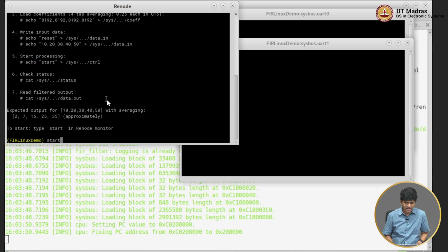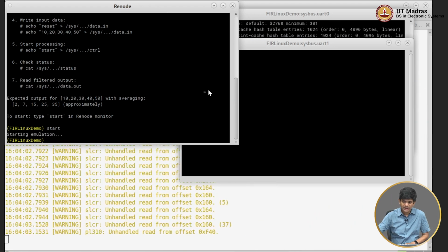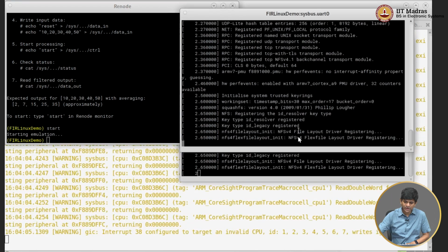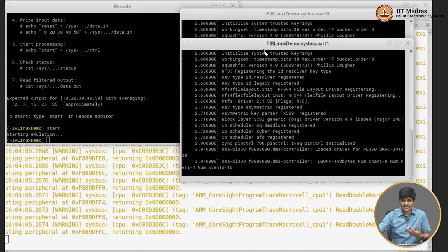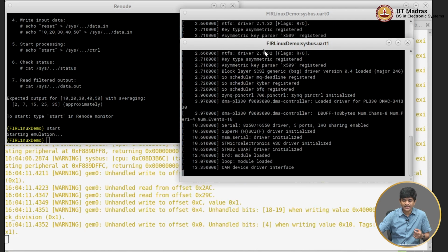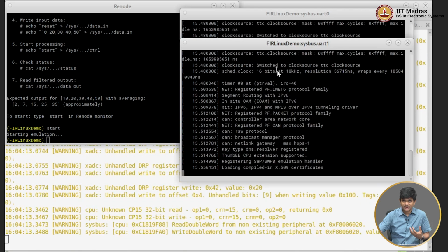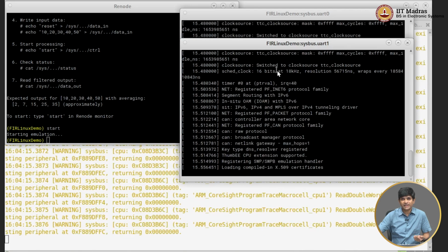So I'm just going to go ahead and start booting into Linux, and this behaves exactly the same as what it was before, right? First messages start coming up on the UART0, which has been connected directly in the kernel command line, and afterwards UART1 kicks in because that is what is specified as the actual console, once the drivers have been activated, right?